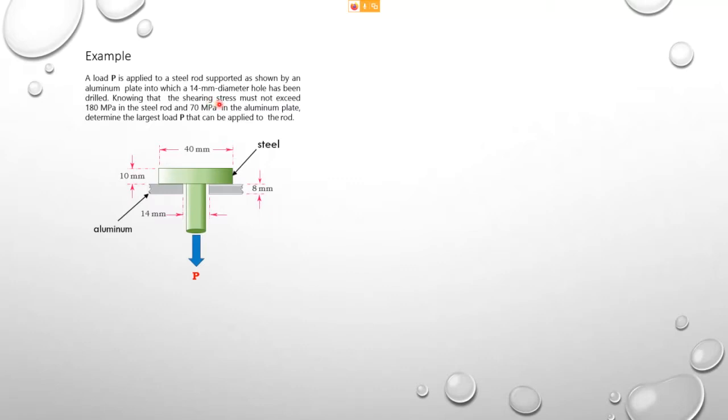Knowing that the shearing stress, now given here is shearing stress. So when you deal with shearing stress, remember the area that is resisting the force or the load has to be parallel to the line of action of the force. Has to be parallel to the line of action of the force.